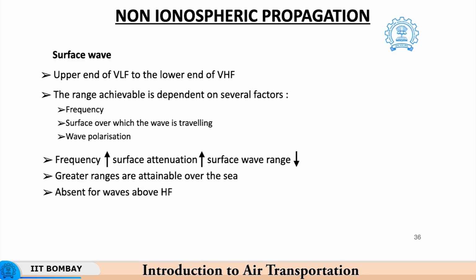As the frequency of operation increases, the surface attenuation increases and hence the surface wave range reduces. On the other hand, if the communication happens over an oceanic region wherein the surface is smoother, the range of communication is increased drastically, whereas if the frequency is very high, this type of propagation path will not be possible and will hence be absent for all frequencies above high frequency.